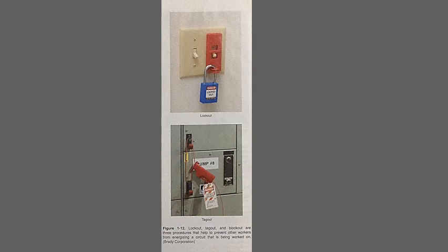Opening a circuit does not mean all energy has been controlled. The power of a fan, for example, may be turned off and locked out, but if the fan blades have not been locked, there is still a possibility of injury. Air movement from another fan could cause the blades to move with enough force to cause injury. Also, switches have been known to fail and close a circuit. In this situation, a lockout device will not prevent the machinery or circuit from running, but a blockout device will.